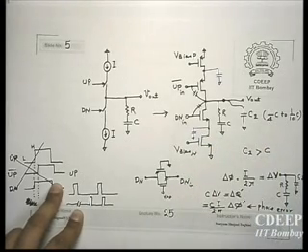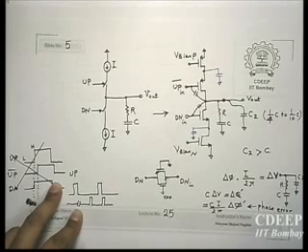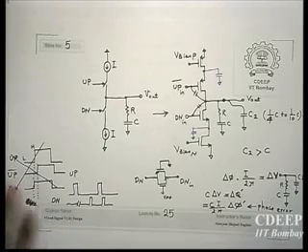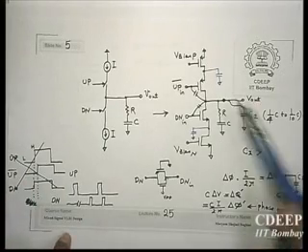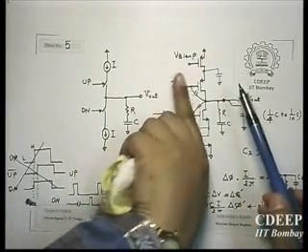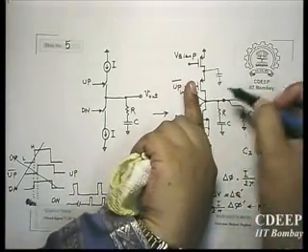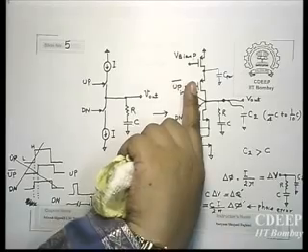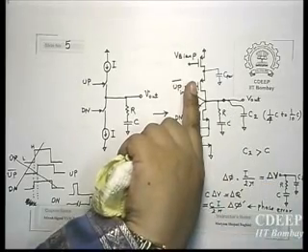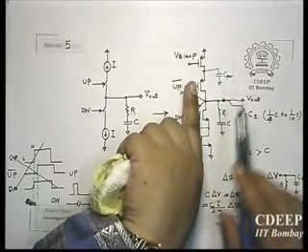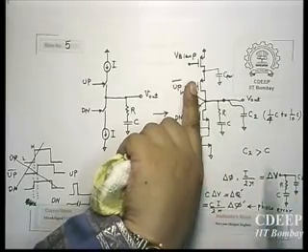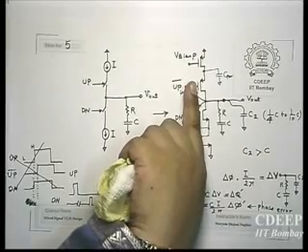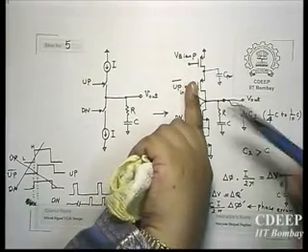So another issue would be that now their voltage is 0 or it is VDD. Eventually it's a very high voltage or a very low voltage compared to the scale we have, from 0 to VDD. Therefore now this switch is on at the beginning. Now you imagine what happens. So this is a C parasitic which is completely charged to VDD. And then you have some output voltage here. So for example, this is 2 volt and VDD is 2 volt and your output voltage is, say for example, 0.8 volt. And now this switch is closed.